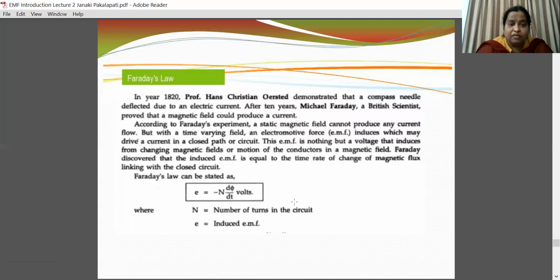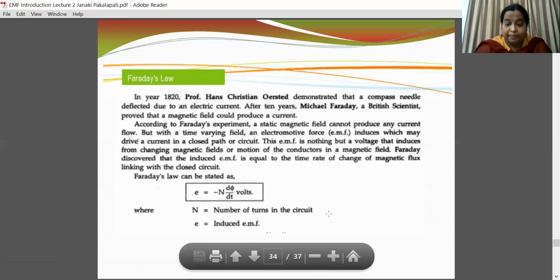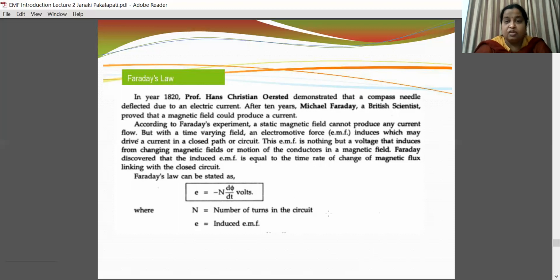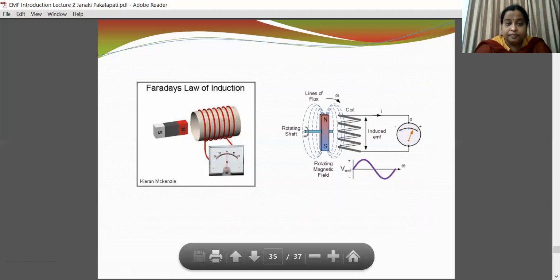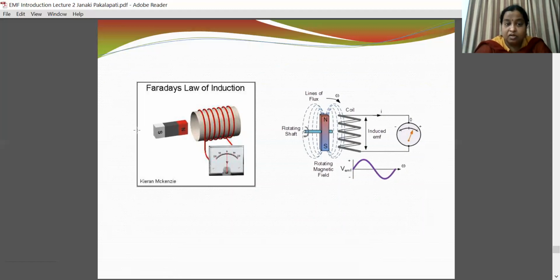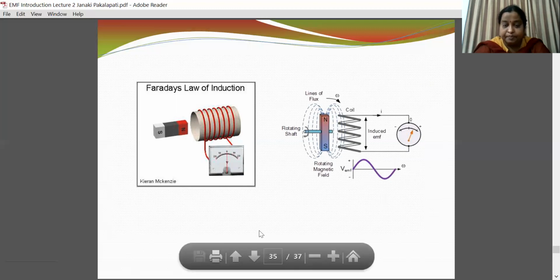And this is your Faraday's law. In machines, we use this for both a generator as well as a motor, where EMF is developed. So what is the EMF developed? Minus N d phi by dt. How is it developed? Based on Maxwell's fourth equation. If you see in this picture, there are north and south poles, representing Faraday's law of electromagnetic induction, with a current carrying wire. If a magnet moves inside and outside like this, EMF is developed, and that EMF developed is alternating in nature.